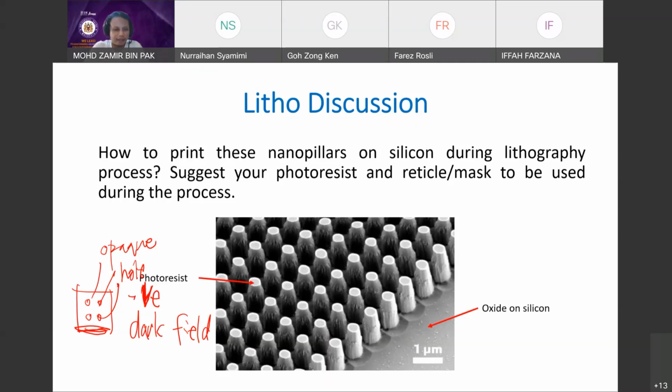Yes, that's the word, hardened, right? So the exposed area will be hardened due to cross polymerization of the polymer. Okay, resist is a polymer, light sensitive polymeric compound. So there'll be cross polymerization, making the structure stronger, and therefore it will not be soluble in the next process that we call developer or removal of the resist.